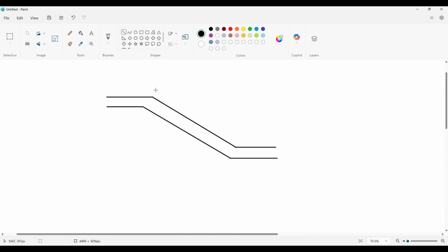All right. Now, when we talk about the tension zones, where will the tension come? So if we just change the color and take this, in the flight part, if I can just draw a straight line, we can just draw a line like this. The tension will be in the mid zone. Why is that? Just a second, let me redraw that. So tension is going to be in this zone because we have support over here, we have support over here.